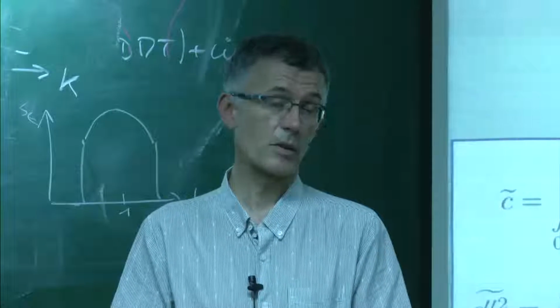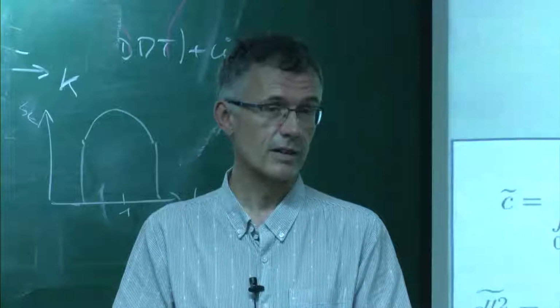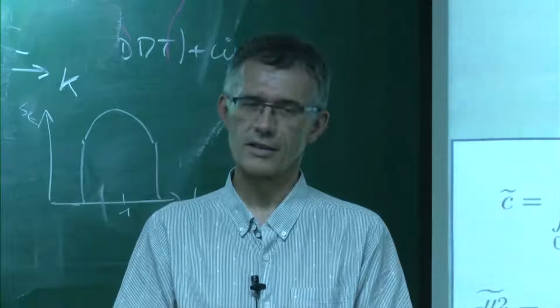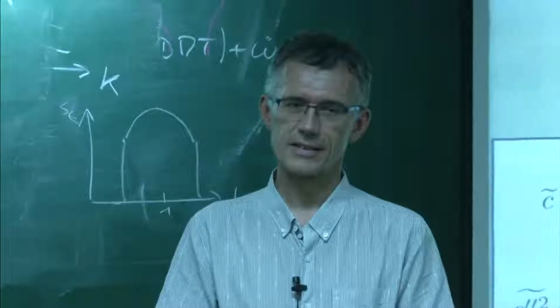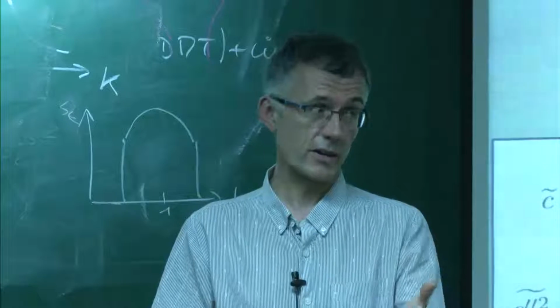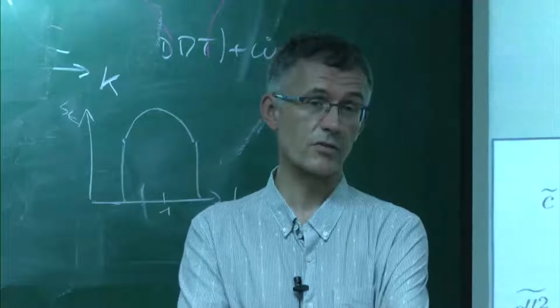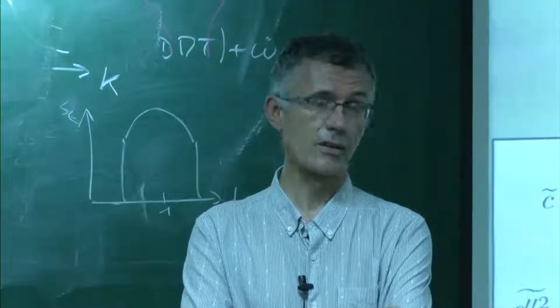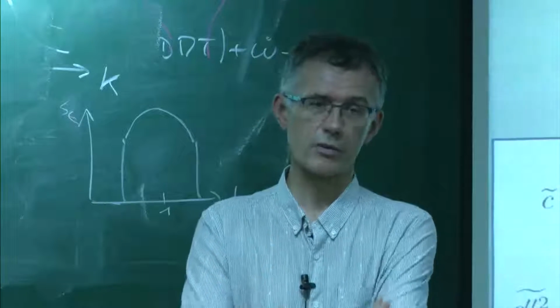Changing the constant, especially by a large amount, should tell you that something is strange. I mean, it should not be done. But for eddy breakup, the constants are changed by a factor of 1,000. With eddy breakup, typically you have to go from 1 to 1,000 to make it work.